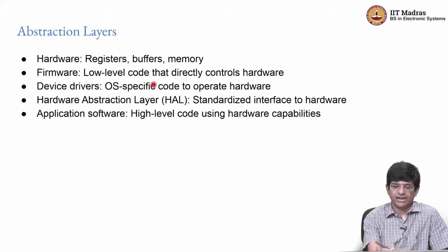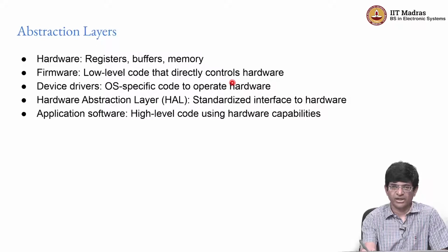The firmware, on the other hand, provides you with one higher level of abstraction. It basically says that you have some slightly low level code that directly controls various kinds of hardware. You have device drivers which are effectively building up what's called the operating system layer, right? They interact with the hardware, but they provide an abstraction to the software, which for example allows you to call a function like send byte to UART rather than going in there and directly setting the individual registers in the UART, setting it to transmit mode, loading the buffer, then activating it and so on.